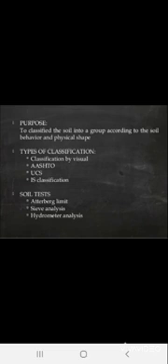So what are the different soil tests in the laboratories to find the nature of the soil? Very first one is your Atterberg limits. Second is your sieve analysis. Third is your hydrometer analysis. The first two are important and easily available in the labs, that is your Atterberg limits, with which we find the plasticity and liquid limit of the soil, and we can also find the specific gravity by a different test, by the use of a pycnometer.